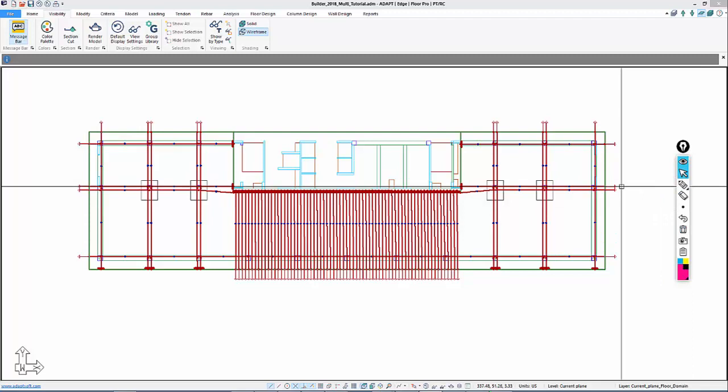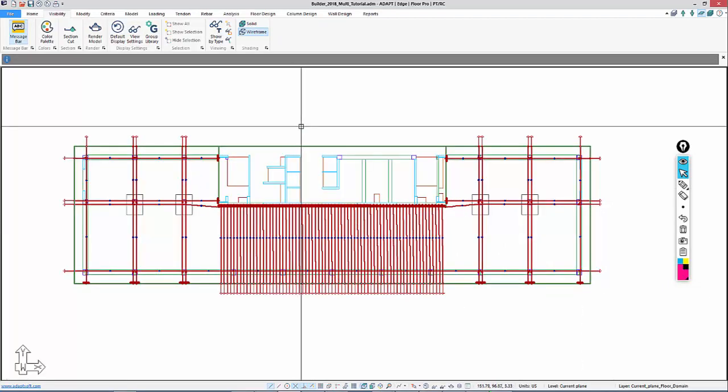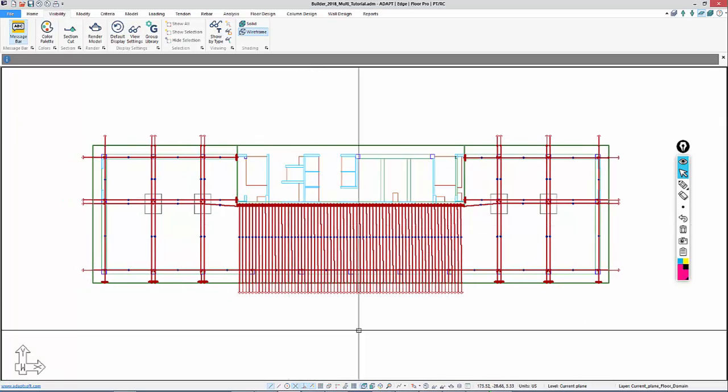We're now going to analyze the structure. So we've defined our load combinations, we've defined our strips, we've input our tendons. We now want to check pre-compression, stresses, balance loading. We're not going to go through each and every problem region within the slab, but we're going to pick one support line and take a look at that particular support line and just make some general comments about the results for the design. And we'll show also the use of the optimizer in this segment.